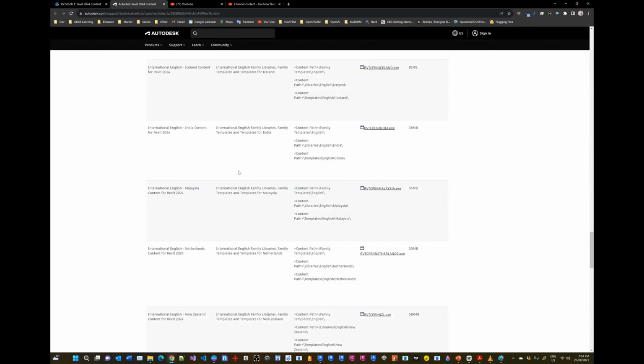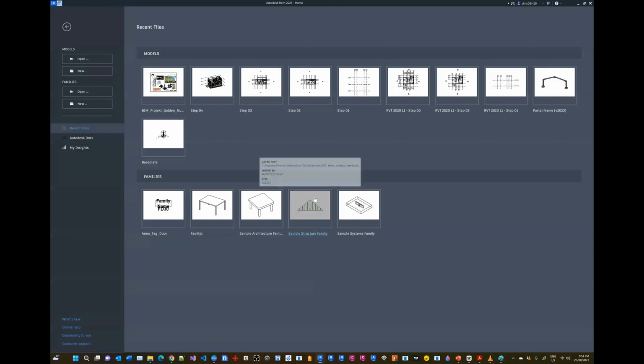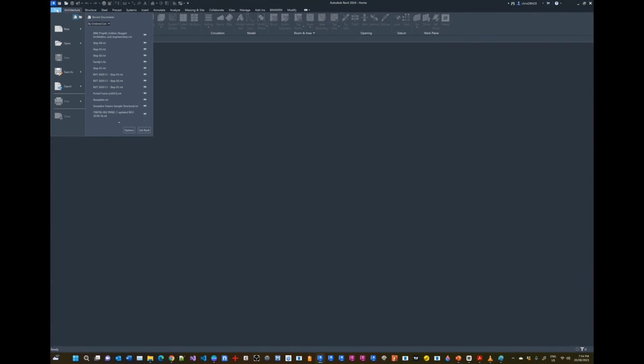And once you've done that, then you can head over to Revit and we can start setting up our options in Revit to show us these templates when we create a new project, that it is the correct ones. And once we've created a project, if we want to link to libraries and content, that we make sure that it's from the relevant content packs. So to do that, we need to go here to the home button view and toggle the home view so that we can see the project view. We click on the file button here and then we choose options.